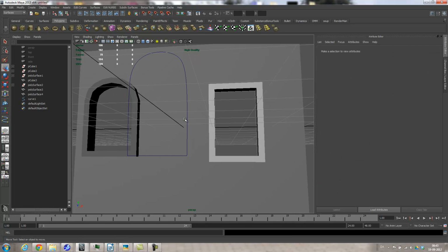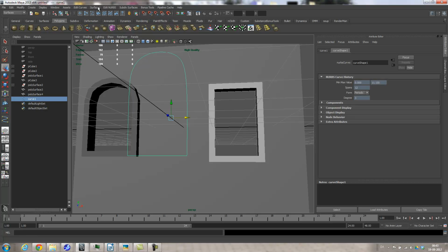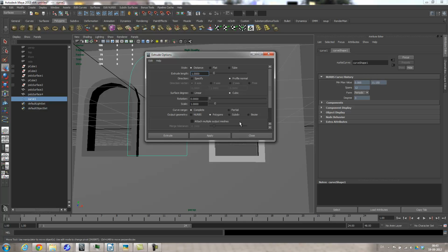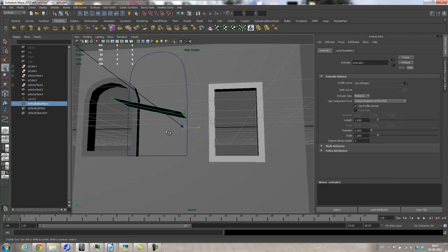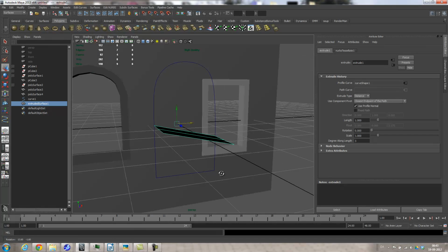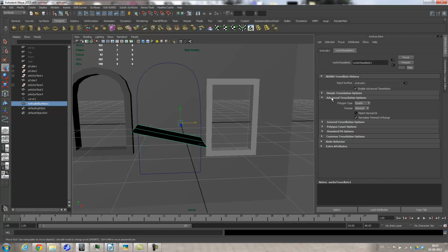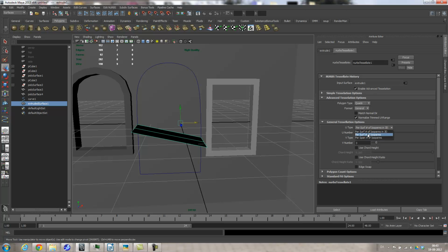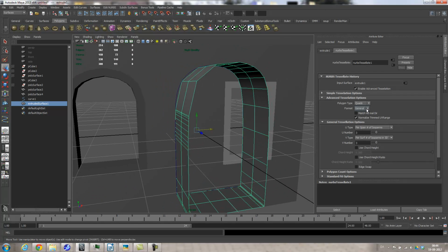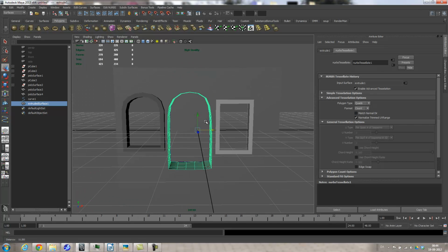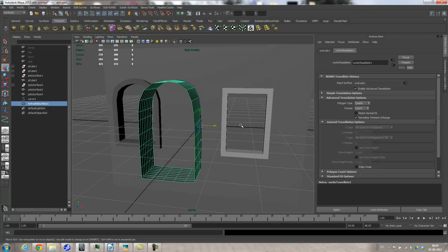Alternatively, instead of using control points, I can use a different way. So I go surfaces, extrude options, set this to distance, polygons, and then set this to general, for instance. And if I then set that to quartic, it will create a quite interesting piece of geometry. I could also change this to count, something like that. So it creates a surface from the NURBS curve.